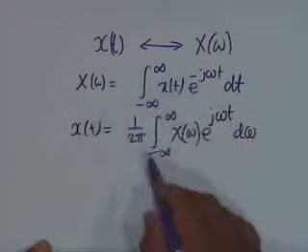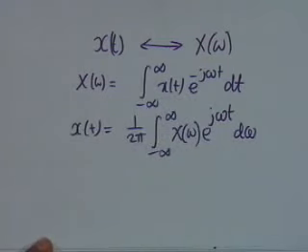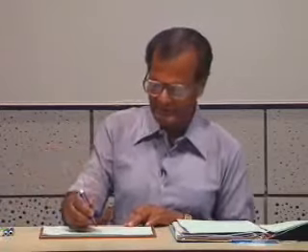We also considered the question of existence and convergence of the Fourier series. We basically discussed two types of conditions. One is that the signal is an energy signal, and the other is that it obeys Dirichlet conditions. One contains integrability of x t mod squared, and the other contains integrability of x t mod, absolute integrability, in addition to two other conditions on maxima and minima and discontinuities.